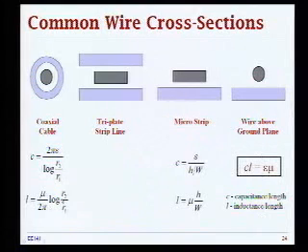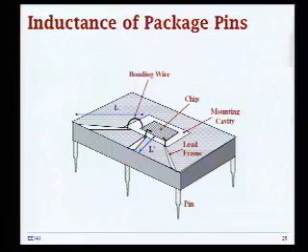For all other cases that have a little bit more complicated unit length capacitance and inductance, we can derive some equivalent C and L that will fit into this expression that relates nicely the speed of wave propagating through the dielectric and your material properties. So this is basically the environment that we want to analyze and apply this theory to.